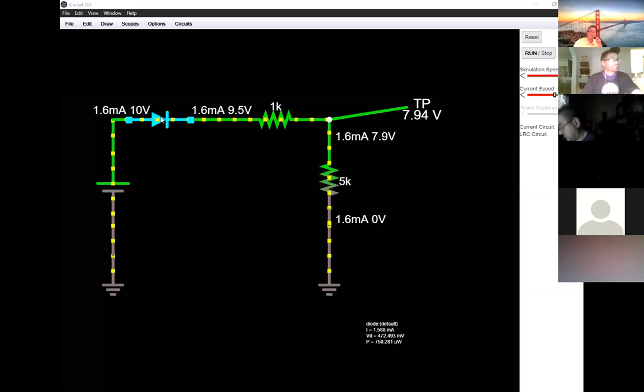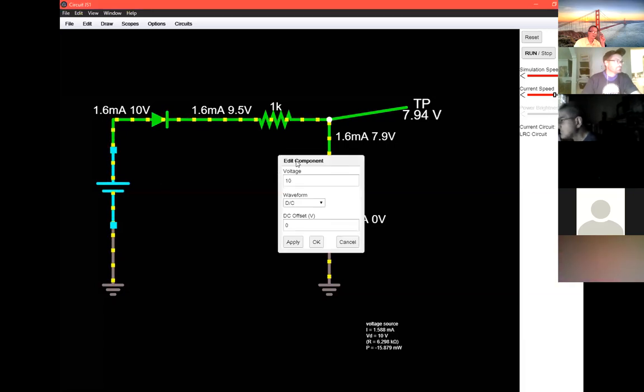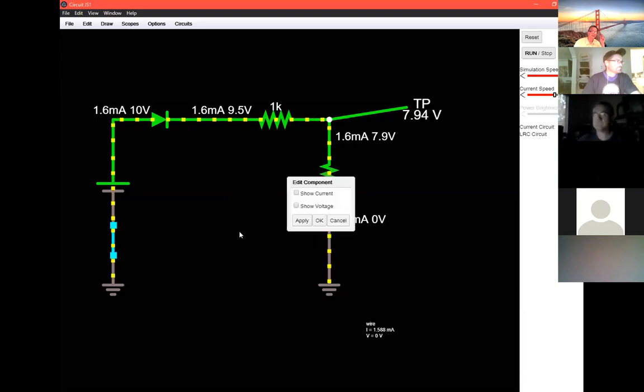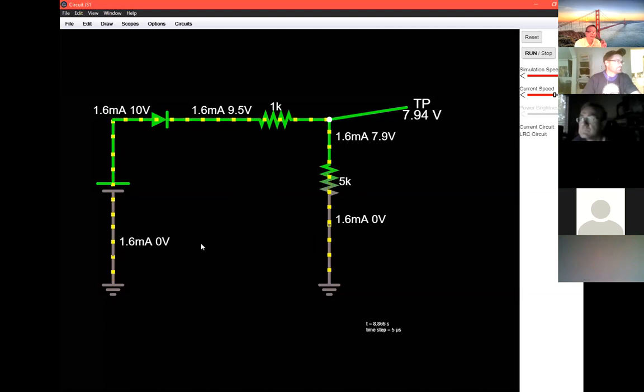Hey, I'm just asking, Lowell, did he want like the 10 volts down by the battery, and then where the diode is at, put like 0.7 or something like that? Is that what it was? Yeah, they're supposed to be 0.7. However, on this, it's 0.5. So that's why 10 minus 0.5, you can get 9.5 volts. So this is not a silicon?